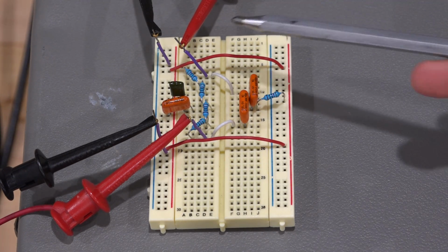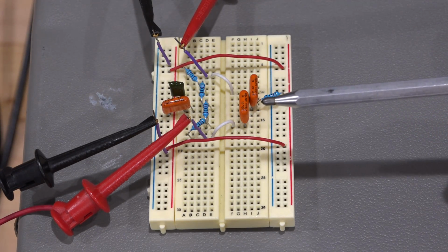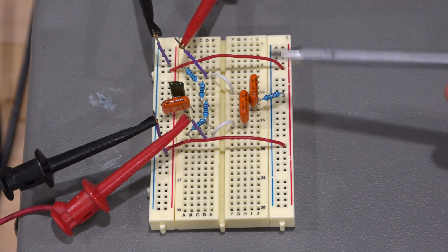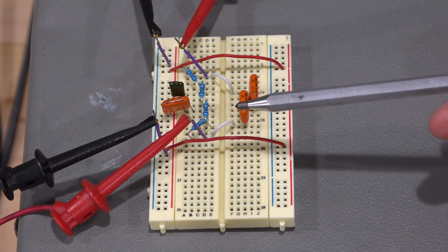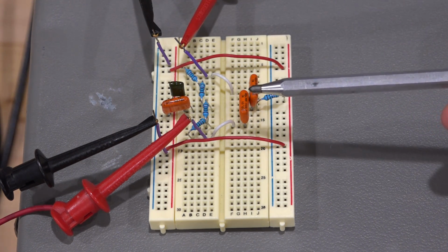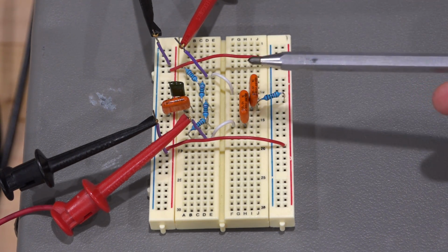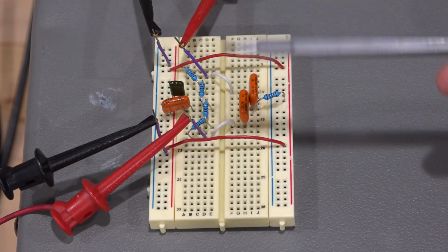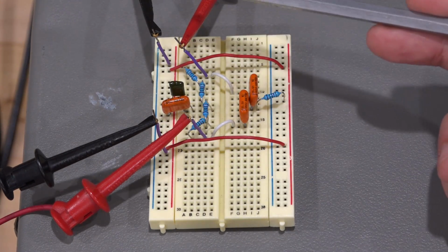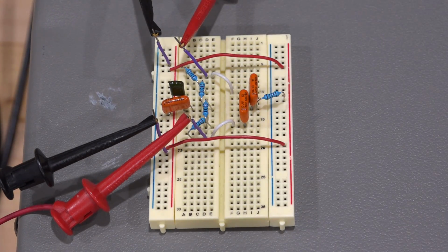And here's our filter. Now, I'm not using exactly the same resistors I showed you because I didn't have a 7.8 kilo ohm resistor. These are 10 kilo ohm, and that moves the center frequency notch to about 775 hertz. So that's where we're going to do most of our measurements, which is okay. Now, this is a perfectly symmetric filter, of course, so it doesn't matter which way you connect it. Now this is still a pretty difficult measurement to make.